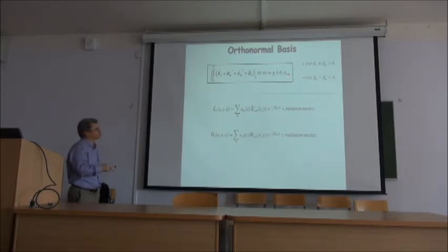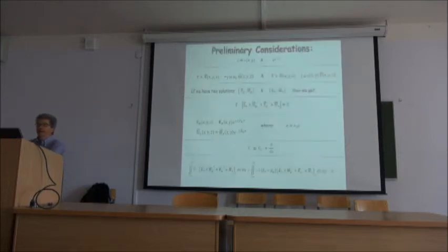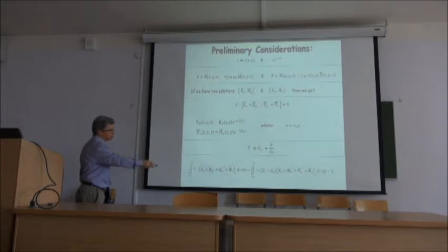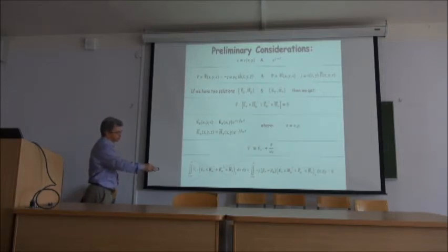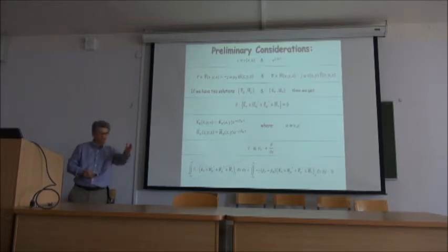And when I have those terms, if the two modes are equal, this term will go to 0, and this term is not necessarily 0, and actually this term here corresponds to the power carried by a mode. To go back to the expressions that we had in lecture 1, when these two indices are the same, that is representing the Poynting vector of our guidance.